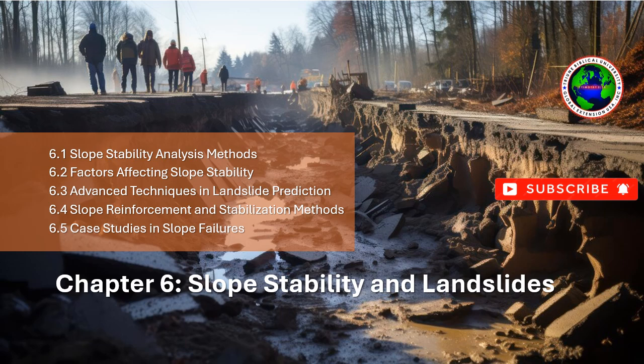Key geological factors: bedding planes and stratigraphy. The arrangement and orientation of bedding planes can significantly impact slope stability. Slopes composed of layers of rock or soil with weak or low shear strength parallel to the slope face are particularly vulnerable to sliding along these planes.